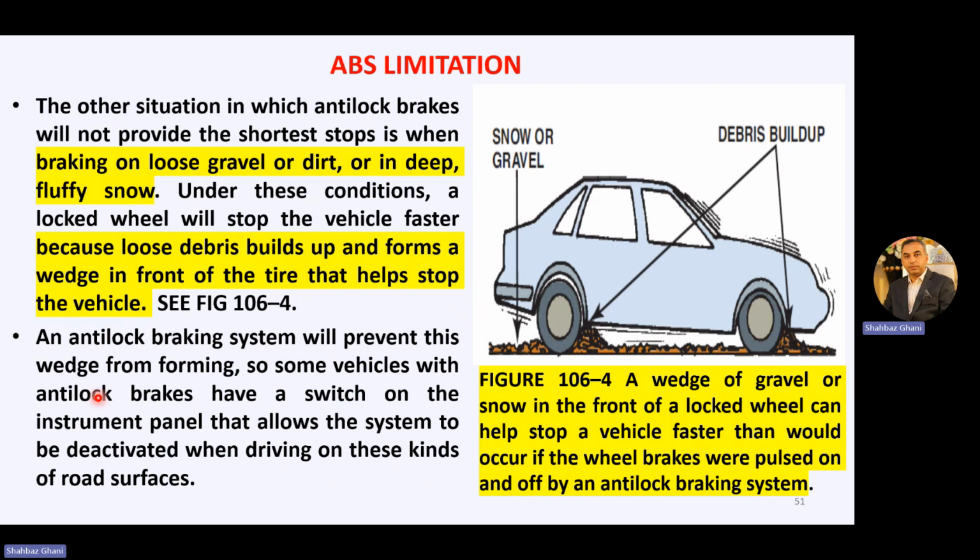Some vehicles with anti-lock brakes have a switch on the instrument panel that allows the system to be deactivated when driving on these kinds of road surfaces. To avoid this type of limitation, some vehicles are equipped with a switch on the instrument panel. If we switch it on, the anti-lock braking system is deactivated